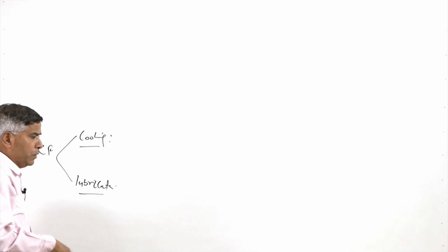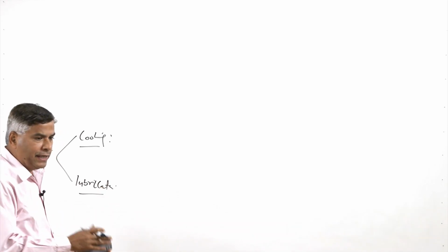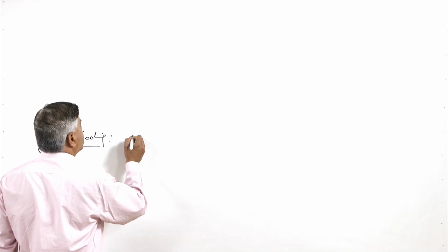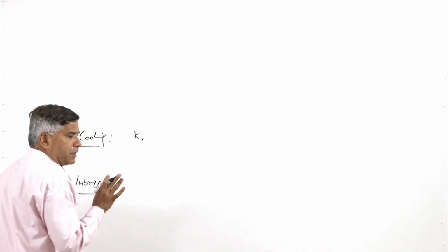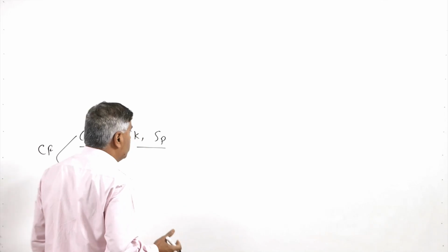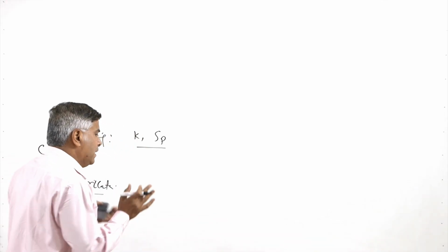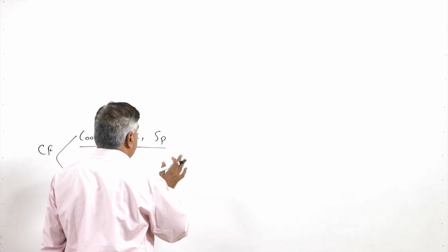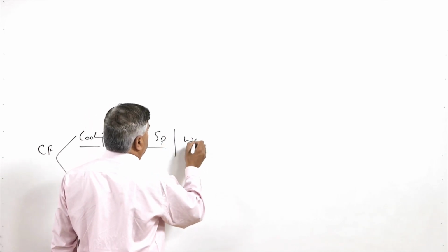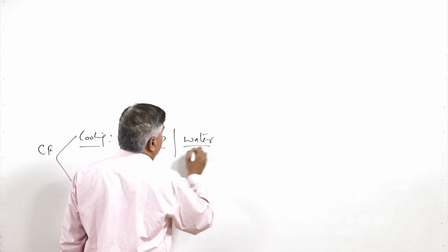For cooling purpose, it is required that heat is carried away from the cutting zone effectively. It is necessary that thermal conductivity of the cutting fluid is good, and the specific heat of the cutting fluid is also good, so that heat can be easily cleared away from the cutting zone, tool and the workpiece, and both these properties are good with water.